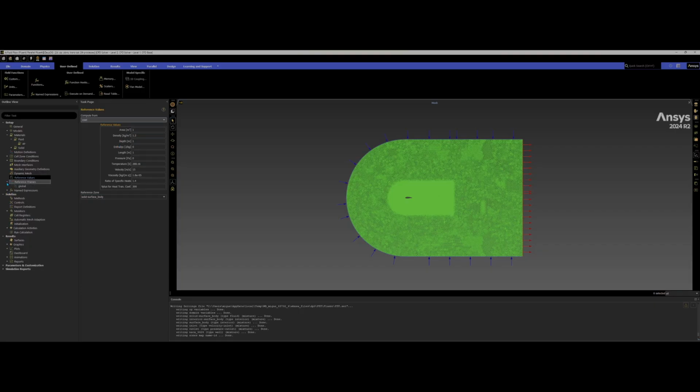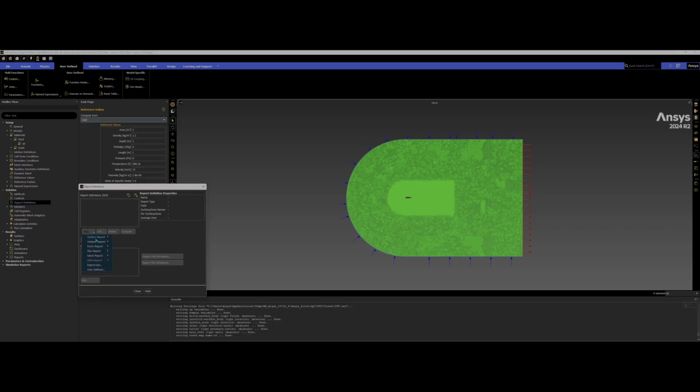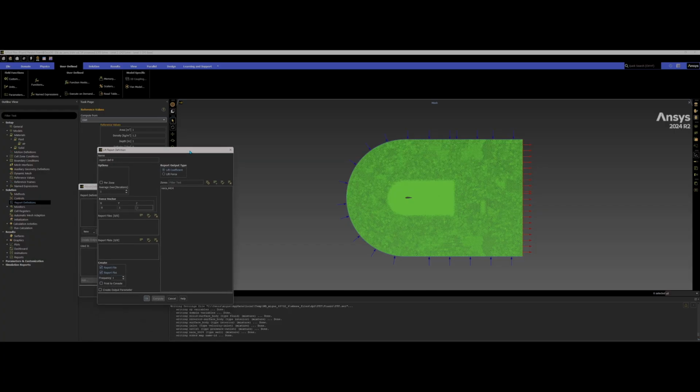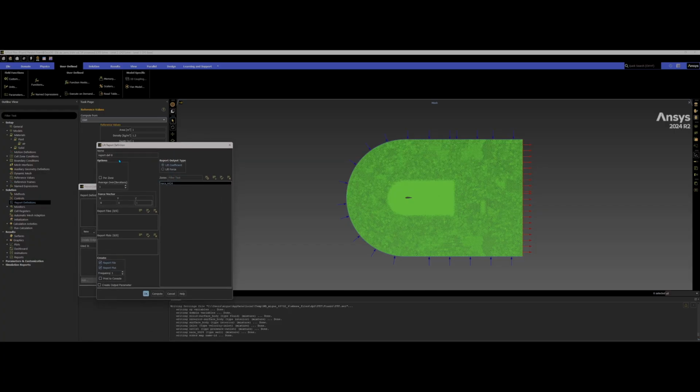Name expressions are there, so it looks good. Now we do our report definitions. I'll do some for both force and lift. The project only requires coefficients, but I'll do forces just to see if my coefficients are correct. That's why I would use lift forces, just to see if my coefficients look right. I could just calculate myself. So, lift coefficient right here.